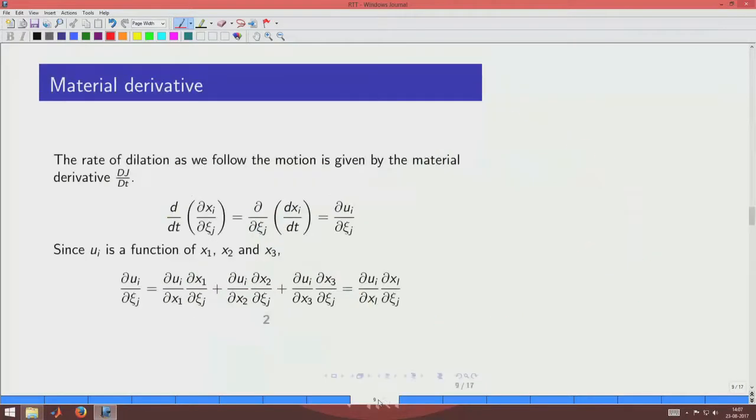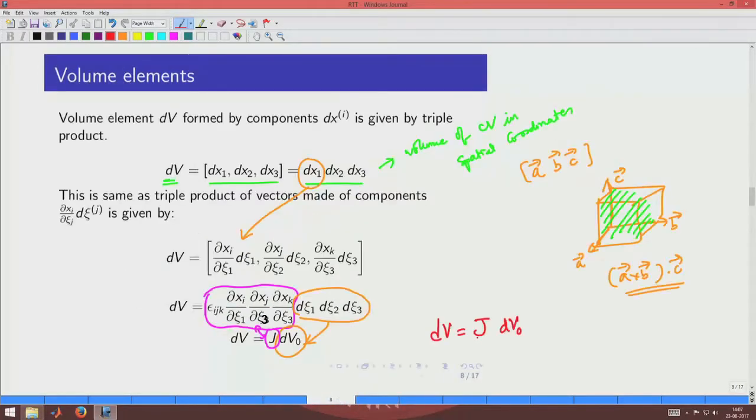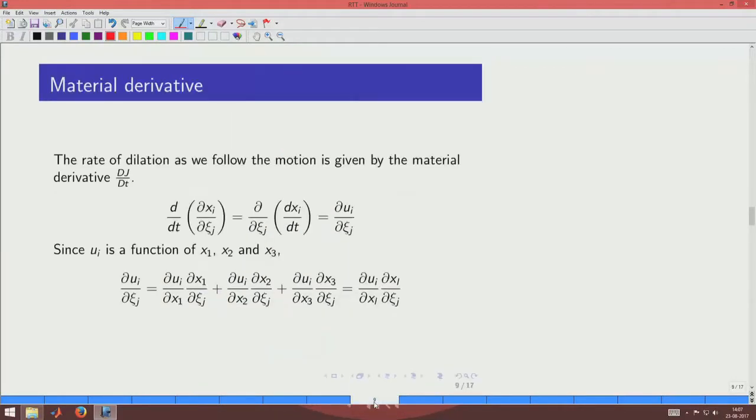Okay. So, this relationship is useful. We are going to use it later on for changing the coordinate system as we need, and we can now see what would happen when we take a material derivative. That is, we take the complete derivative in the Eulerian specification and see how these quantities are going to change. So, we need two terms for our derivation. The first term and second term are listed here.